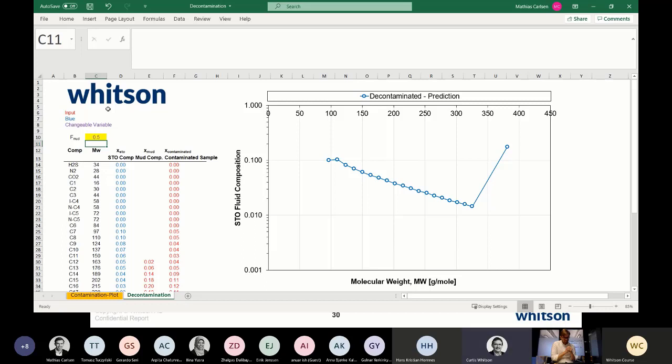So that gives you a starting point, an estimate of the mud fraction. What we do internally is more sophisticated, like Bilal was talking about, where the molar distribution shape, which we'll come to later, that will give a curve instead of a straight line on this plot, is known from other samples that have no oil-based mud contamination. So we actually know the molar distribution, be it exponential or non-exponential.